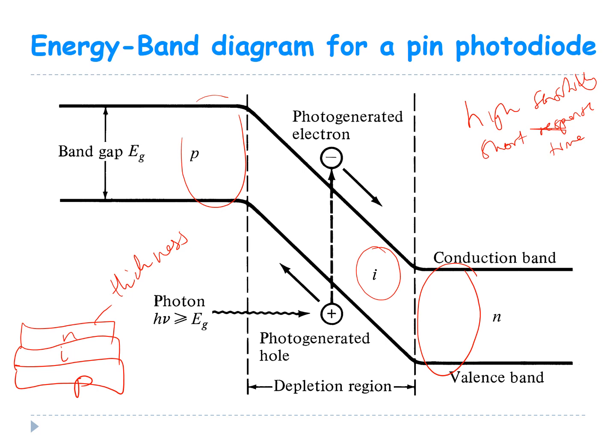thickness, because if the N region is too thick, all the absorption is going to occur in the N region. And if you've got too much absorption there, then you cannot have further absorption. So you should make sure that the majority of the light that comes in goes to the intrinsic region. So the thickness of these three layers is very, very important in that respect.